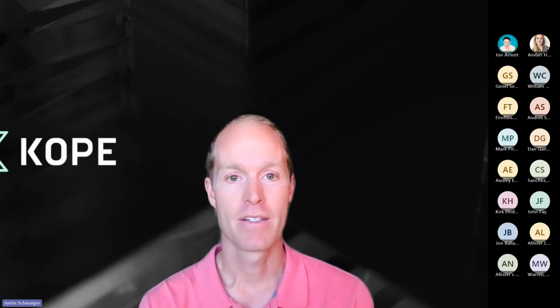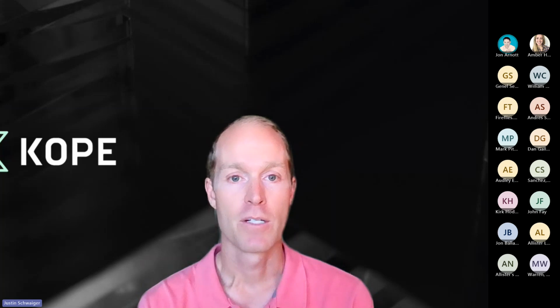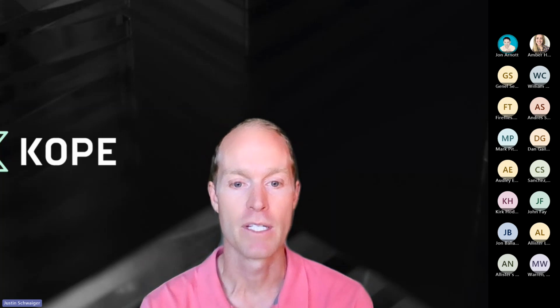Question is, have you had any experiences of using CADwork and Cope together? I've had a lot of conversations around that. And again, the workflow that makes a lot of sense is Cope for your coding, and then CADwork for your fabrication level detailing and modeling. And so Cope output as an input to CADwork makes a ton of sense. And again, we're using a very interchangeable format with IFC. So you can leverage that Cope generated system layout and then take it from there and go detail it.